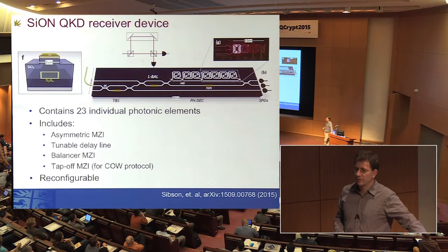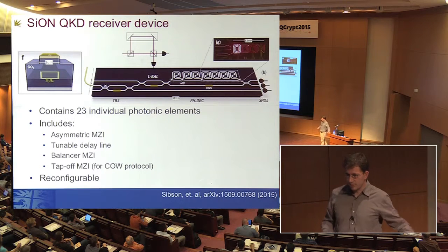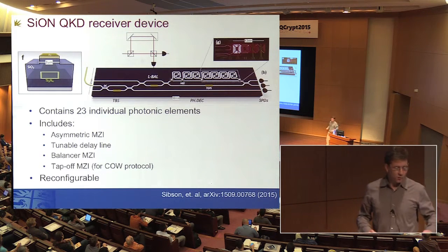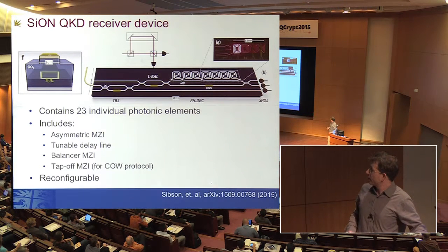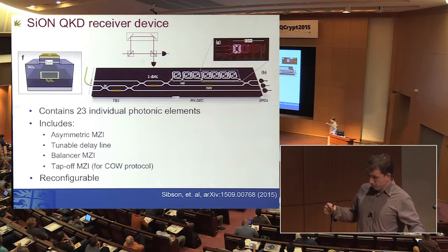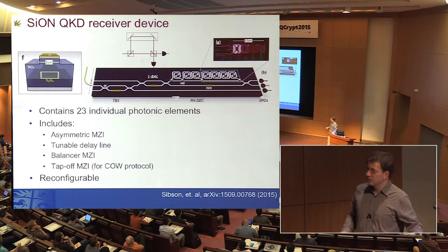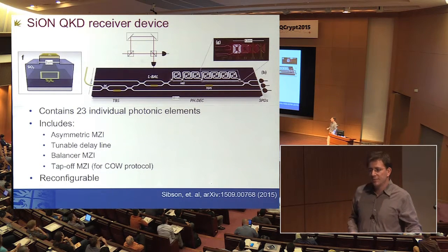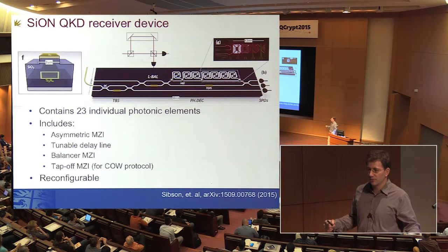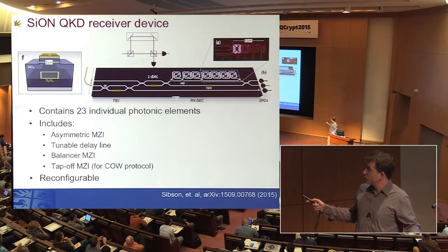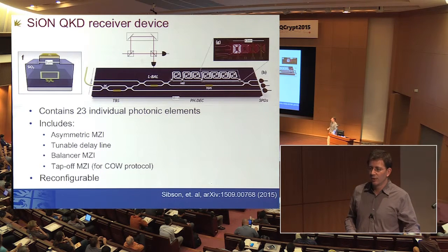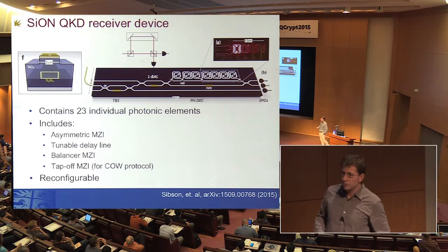The long-term strategy is to look at getting detectors on chip, but we're a good way from doing that. The coupling losses are because of the fact that we're using a glass-based material system. One of the reasons we went for it is because of the low coupling losses. In this case, we're getting about 2 dB coupling losses, which is actually quite high for a glass-based material. So feasibly, we should in future devices be able to get that down below a dB or even half a dB. So really efficient off-chip coupling.